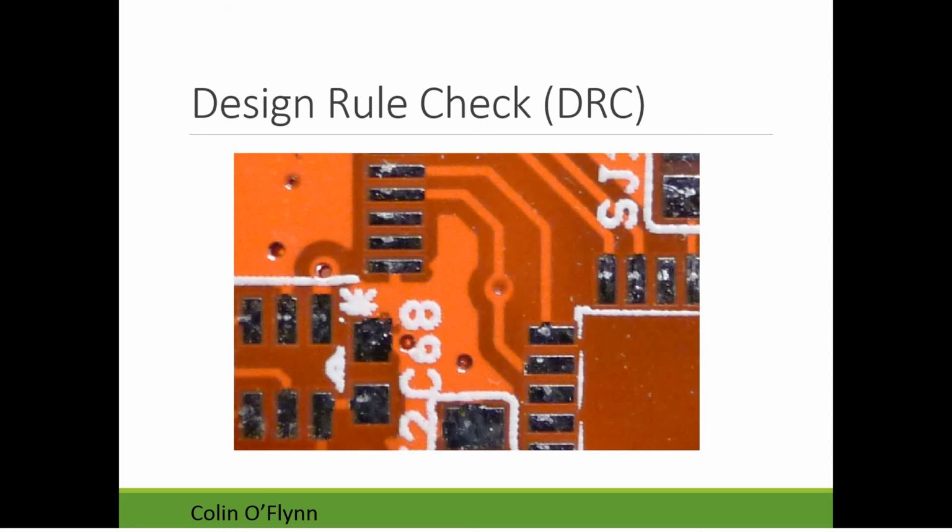And you'll see stuff written like 7 mil. Commonly it will have something like 7 mil, 8 mil, 6 mil. What this means, and when you see 7 mil, it just means 0.007 inches is the minimum trace and space that you can get away with. You always want to be above that if you can.